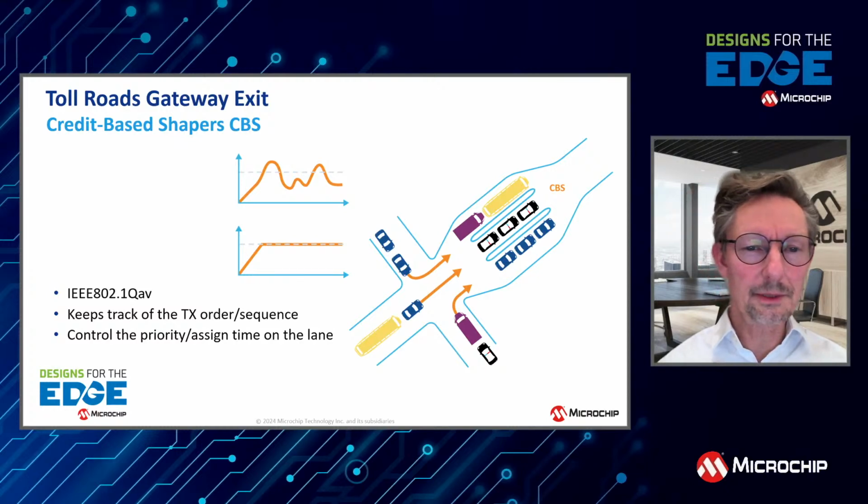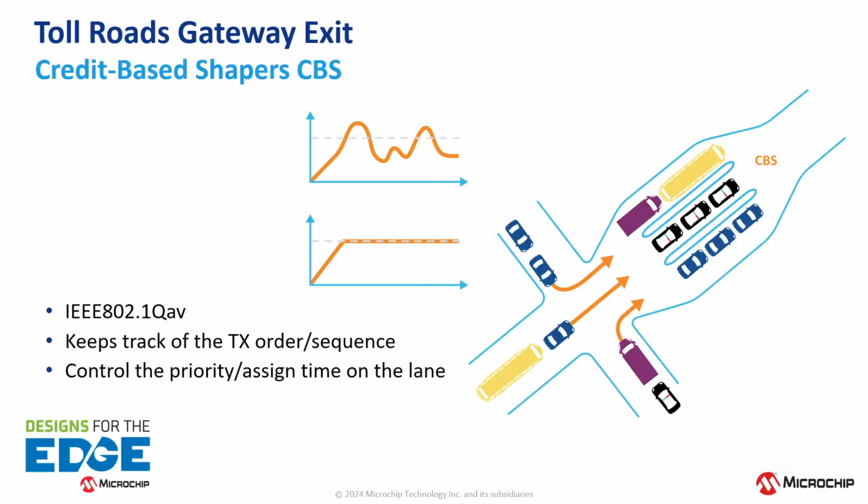In the middle of the picture here, we see some graphs. I have drawn a dotted line. This is the bandwidth maximum, the maximum capability of the line. We can see here, if you're not applying the CBS TSN feature, there might be some burst effect on the line, in very congested times. All this burst over the bandwidth line will basically not come through, so we need to resend all those frames from that time part.